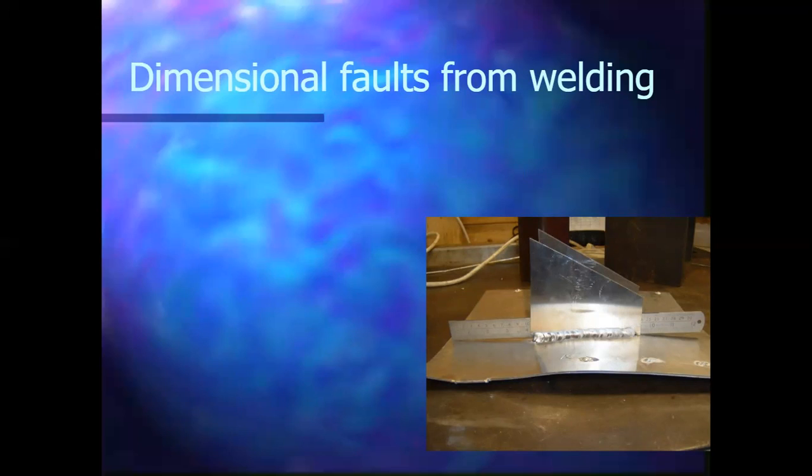So when we're welding with thin material, we want to put as little heat into it as possible. MIG, or gas metal arc welding, is great for thin sheet metal. If you turn it down low, you run a small wire. Gas metal arc welding is one of the processes that puts the least amount of heat into things, because shielded metal arc welding is going to be much hotter. Flux core arc welding is way hotter. TIG welding is pretty darn hot too. So something that puts in a little bit of heat, such as gas metal arc welding, is something I would probably choose, maybe TIG.